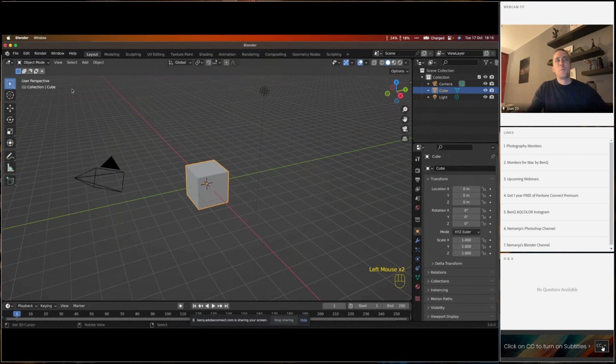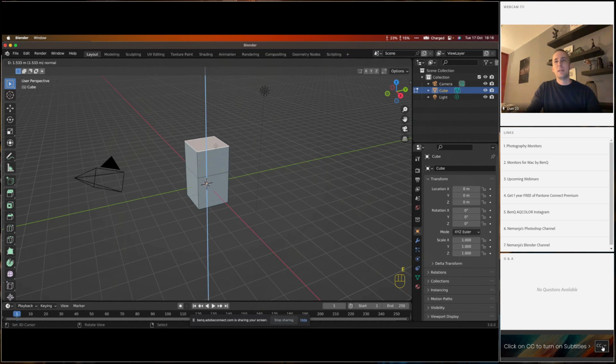The two most used modes in modeling are object mode and edit mode. In edit mode, we have these vertices, which are the points of the model, and also edges, and also the faces. And we have the representations here, what they are. Basically, we are modeling things in Blender by doing extrude with keyboard shortcuts, like here you can see what I'm doing with my mouse.